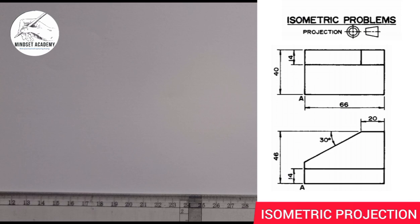We want to reproduce the two views displayed at the right hand side of the screen in isometric projection. If you look at these views very well, this here is the front elevation and this here is the plan. Why? Because it is in third angle projection. In third angle projection, the plan is always on top of the elevation.